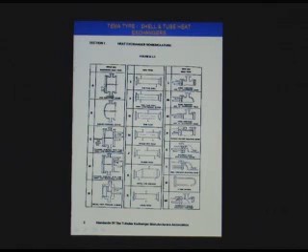We have an A-type channel where we have a full bolted cover. B-type is where we have a bonnet type. The selection between these two is usually made by the client based on his desire to minimize the number of leaking flanges. This defines the type of tube passes we have.